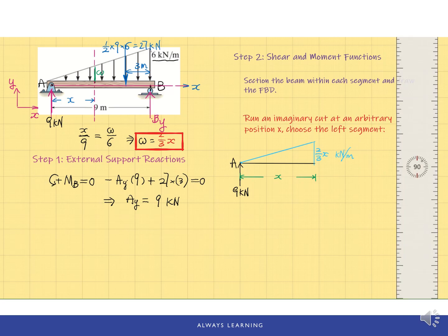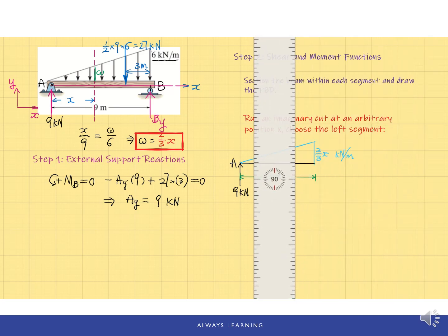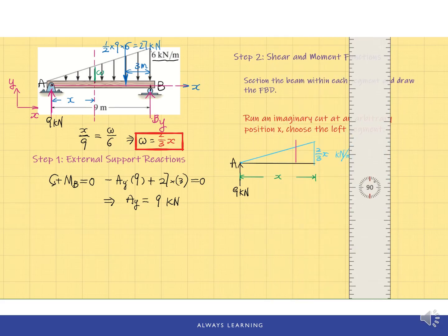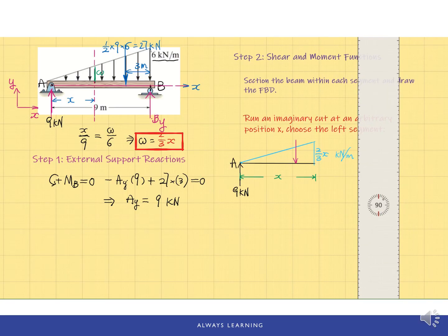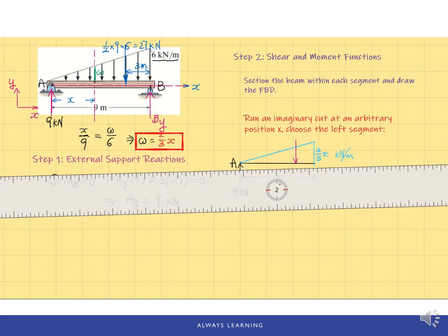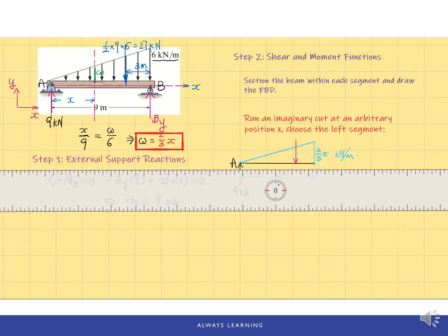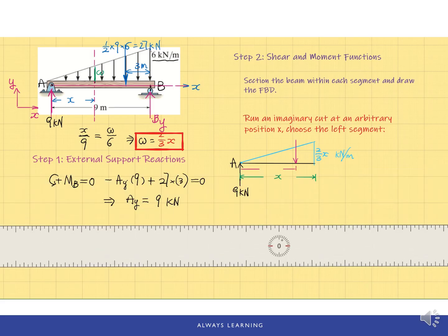Therefore, it should be over here. So 1/3 of x to the right end should be 2/3 of x from point A. So put the location of this concentrated load on your free body diagram. Again, this is used to help you write equilibrium equations. Without this, it's not easy to write your equilibrium equations, and then it's not easy for others to interpret your work as well.